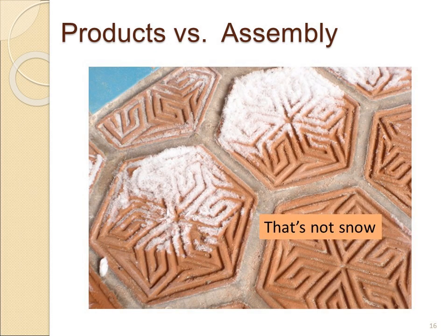And when we think about materials themselves, back in the day when I installed, we always thought, well, if we use quarry tile, we wouldn't have any issues on the project because quarry breathes and we have these nice big grout joints that we no longer have. And moisture will get out and it won't be a problem.